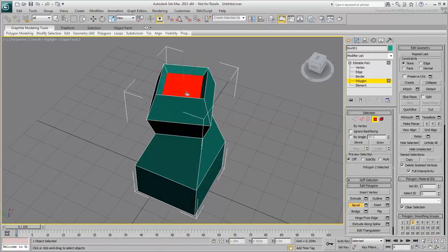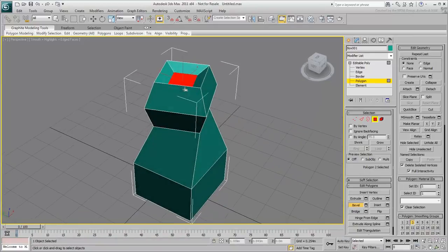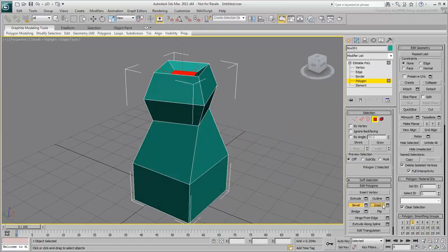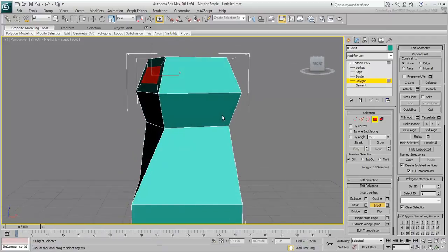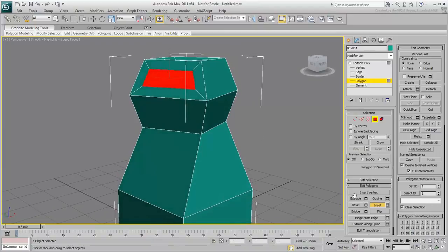Extrusions and bevels can also be negative to punch holes into the geometry. This is very useful if you also use Inset. The Inset command is essentially a bevel without an extrusion. It's great for creating quads while retaining the object's shape. And you can extrude or bevel that.